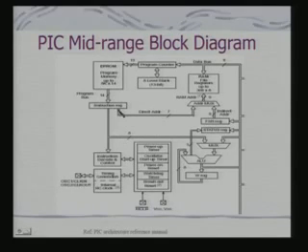One is here I have got the direct address which goes in through the address multiplexer to select the registers, and here you will find that directly the 8-bit data, as part of the instruction, is coming to the multiplexer by which it is fed to the ALU. Now why is this bus there? To enable immediate mode addressing, that is when the data is part of the instruction. And there is also a provision for indirect addressing.